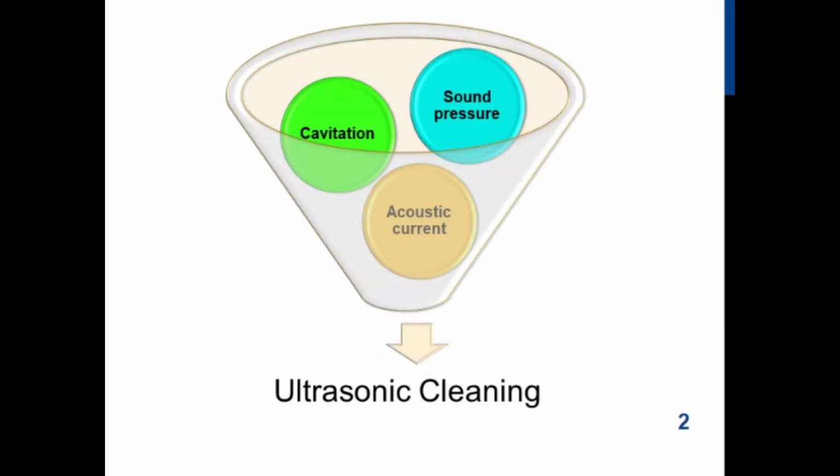The quality and reliability of the products are directly dependent on the degree of purity. So there are many different cleaning methods used in certain industries. This is a combination of various chemical solvents, manual or mechanical cleaning, as well as ultrasonic cleaning, which eliminated the disadvantages inherent in other methods, such as environmental pollution. Ultrasonic cleaning is one of the most effective in terms of quality and cost.